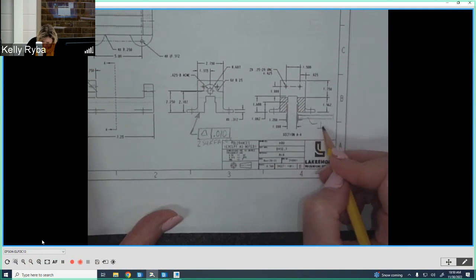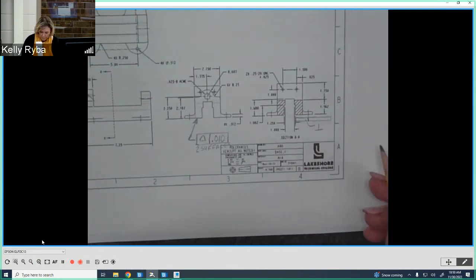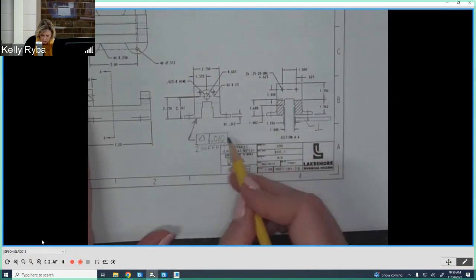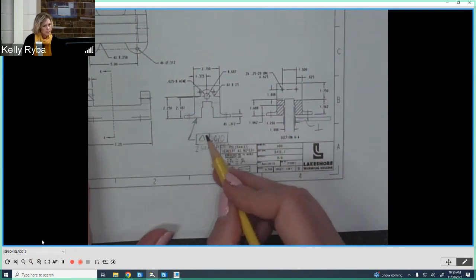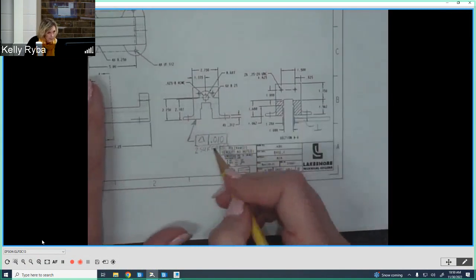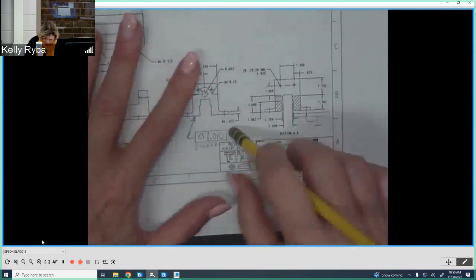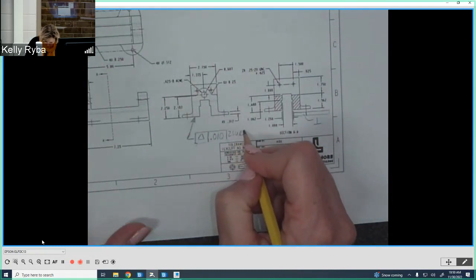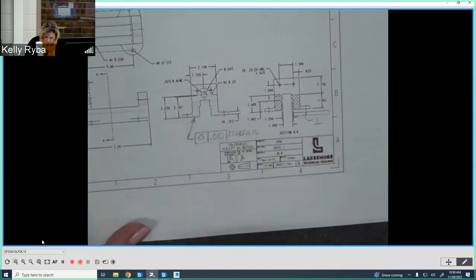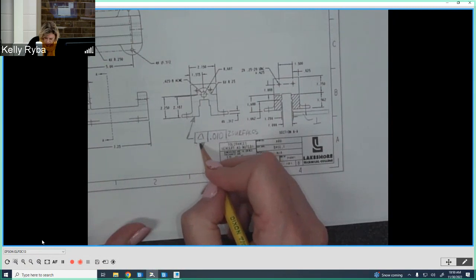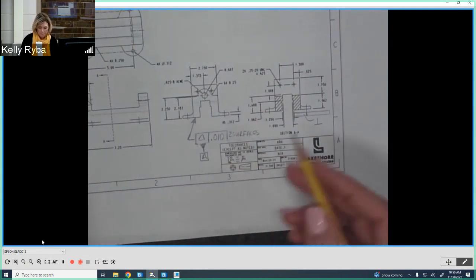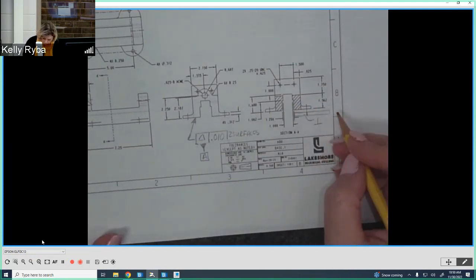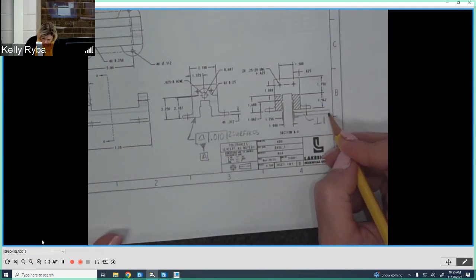This is going to be a perpendicularity tolerance, and we want that to be perpendicular to the bottom surface. So once this has a profile tolerance on it, we are going to make it a datum. All right, now see here that I got to move this. This needs to be 2 surfaces. This is the beauty of CAD, because it's easier to move, but then this is going to have to become a datum, okay? Because I want this surface right here to be perpendicular to datum A, all right?